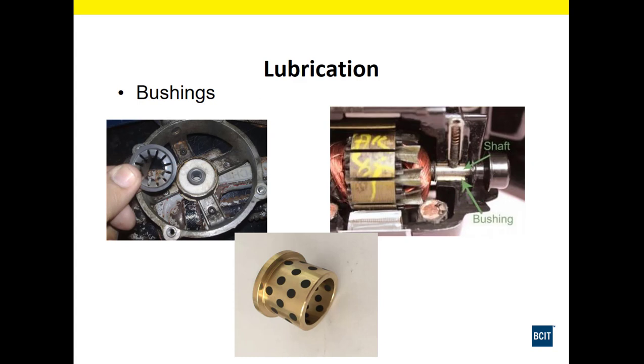Lubricating bushings has a couple different methods. Here we have a felt pad that actually gets saturated with oil, and then as the shaft that goes into the middle of this bushing spins, it'll heat up a little bit and it wicks in the oil as it's required. Here again we have a lubricant inserted bushing, where the lubricant's actually inserted in holes inside of this bushing.